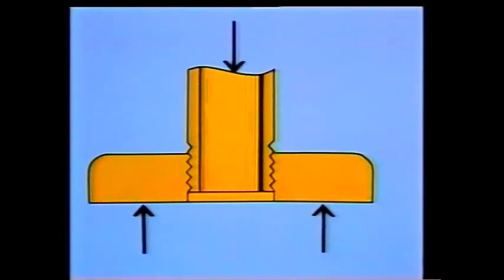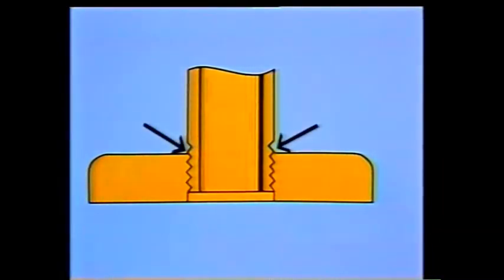This flange is threaded to the pipe. It's done by threading the flange onto the pipe until the pipe end is approximately 1 thread from the face of the flange. This will prevent the pipe from interfering with the flange faces when the joint is made. If the pipe were threaded through the flange, it would prevent the 2 flange faces from meeting and forming a seal.